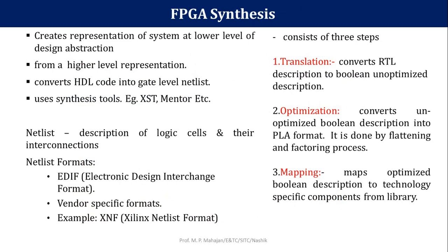Now let's talk about FPGA synthesis. Already we discussed this, but let's summarize. FPGA synthesis creates the representation of a system at a lower level of design abstraction from a higher level of representation. Here, the high level representation is in terms of either a schematic or HDL code, and the lower level is in terms of a netlist, which consists of signals and their interconnections required on your hardware or PLD.